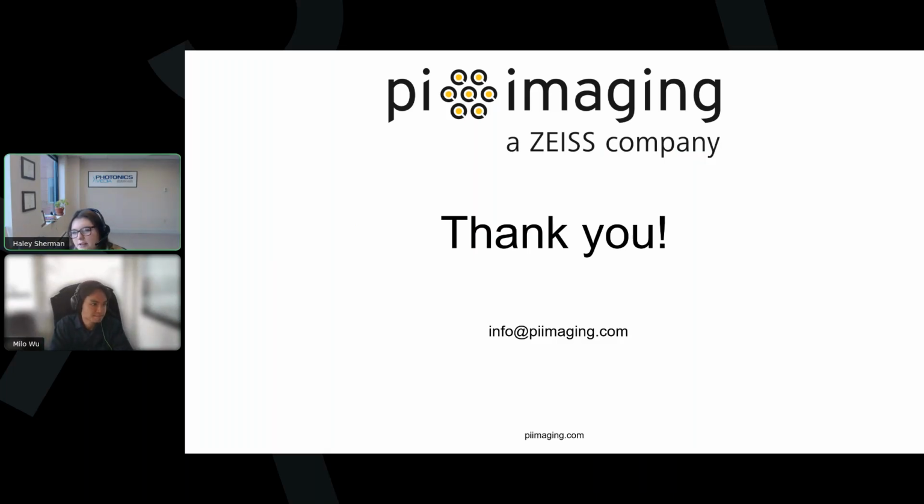Okay, next question I have is, do you have software to perform the correlation measurement, or does the user need to provide this? Typically, this is done by the user. What the user can get from our software is all the time tags, if you have the time tagging option available. Then with the time tag, you can either compare between the pixels or even between two different detectors if you sync them with the external trigger.